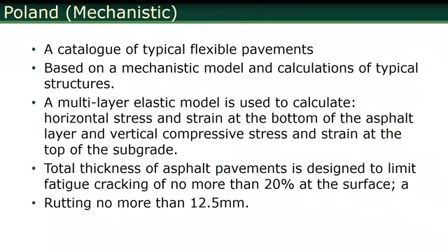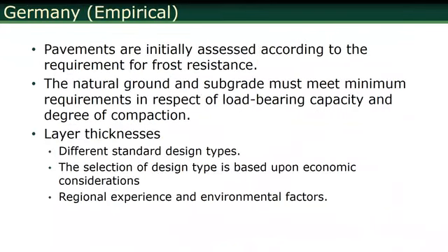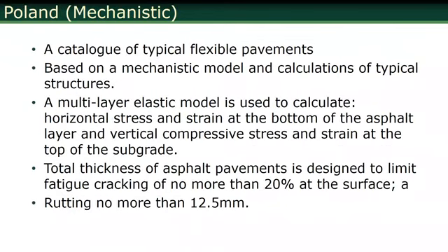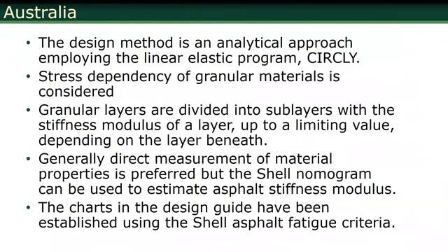Yes? Yes, this is pavement ME, mechanistic empirical pavement design guide type. So running the pavement ME mechanistic empirical design guide many times and coming up with standard thicknesses for different types of regions. Empirical, this is AASHTO 93 type. When I say empirical, usually AASHTO 93 type. Mechanistic is typically pavement ME type designs. Australia, they have pavement ME type.